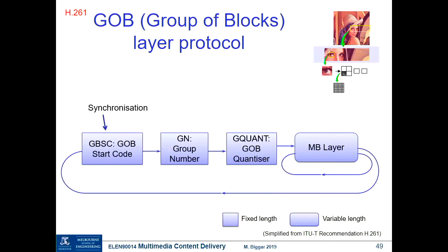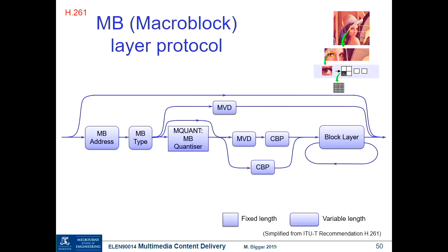Some information might apply to a whole group of blocks, but we might override it for a specific block. And this logic makes sense: you could use just a motion vector, or a motion vector plus some coded information describing the difference signal, and you need to define which blocks are coded, this sort of thing.